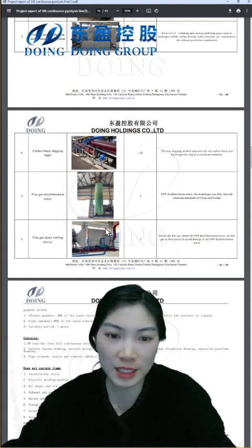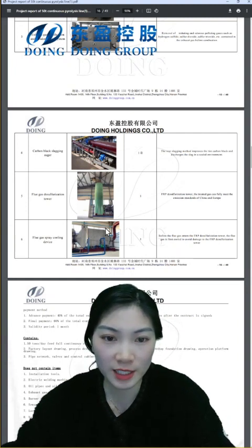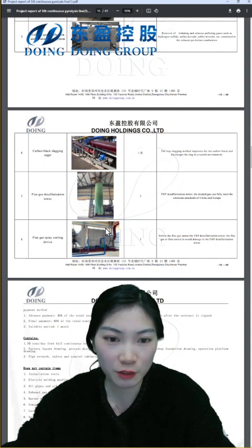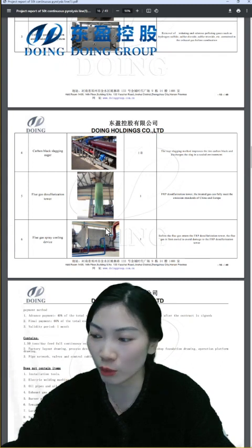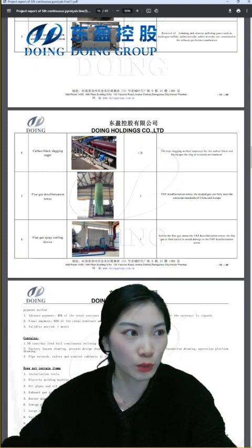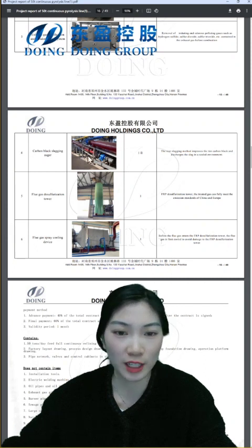You know, for batch pyrolysis plant, we need some time to cool the reactor. After cooling to about 80 degrees, we can discharge the carbon black. But for fully continuous, we don't need to wait for the reactor cooling down. We just discharge the carbon black into the water jacket sliding auger. That's okay.